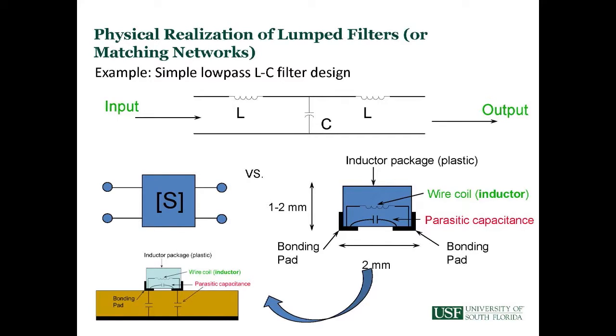When is an inductor not an inductor? When it's a capacitor, until it's an inductor again. Because what happens with RF engineering is there's something called parasitics. If we take a packaged inductor, you have this nominal inductance, but a real inductor has some bonding pads, and there's capacitance between those bonding pads. Eventually, there's going to be a self-resonance, a 1 over square root of LC resonance between those elements. Above that resonance, the capacitor is going to dominate, so it becomes a capacitor. And if that's all there is, then it would be, but it actually gets more complicated than that.